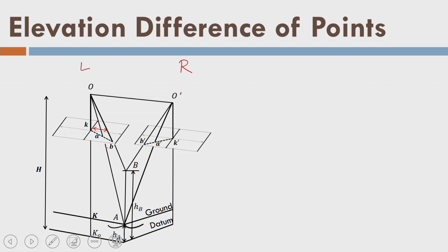So, now we are using the relief displacement in order to find out the third dimension, or the Z dimension, but using two photographs, not one photograph. That is the idea here. So, that is the XA coordinate. Similarly, I have the XA dash coordinate, right. And you remember that we have calculated the parallax. So, this is my XB and this is my XB dash. I hope you agree with XB dash and XA dash.